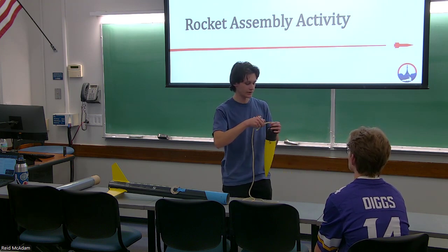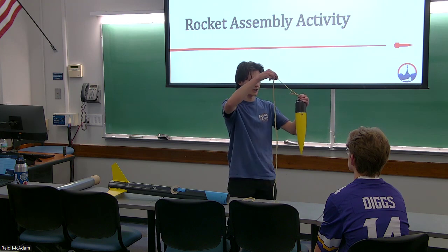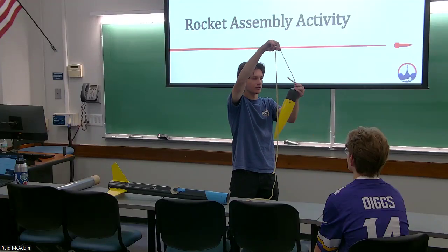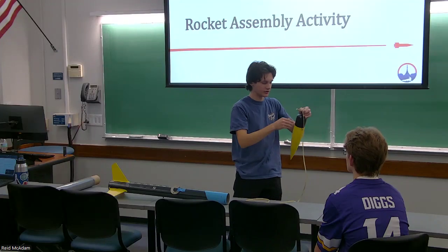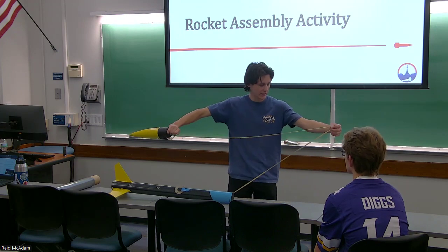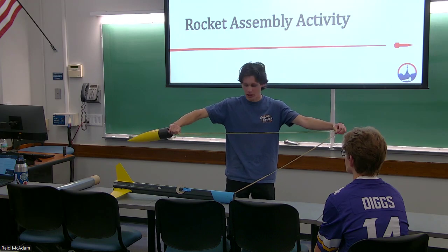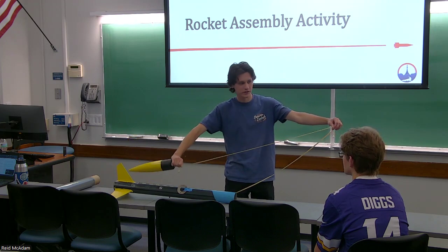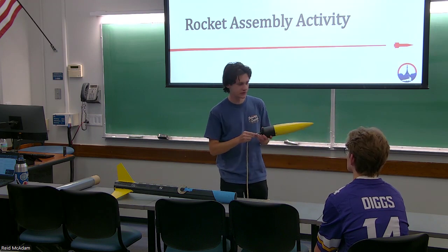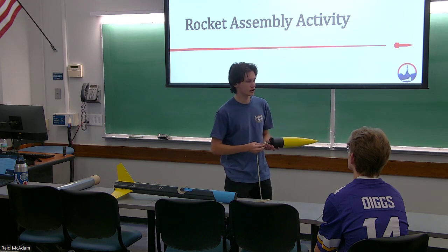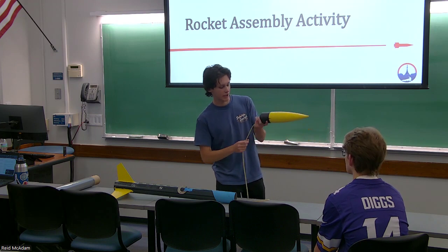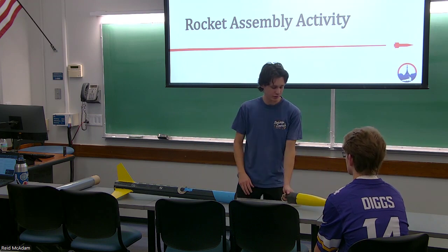Usually when you tie it, you have it closer to one side than the other, because that way when it's straight down and the nose cone is swinging, right now it's only hitting shock cord, and that's fine. Versus if we had it like this in the middle, then everything's under parachute, but when our nose cone swings, it hits the rocket. That's not good. We actually had a problem with that last year for SL. Two of our sections hit each other under parachute, and one of them totally broke off. It fell like 400 feet, and we had to repair it. It was pretty bad.